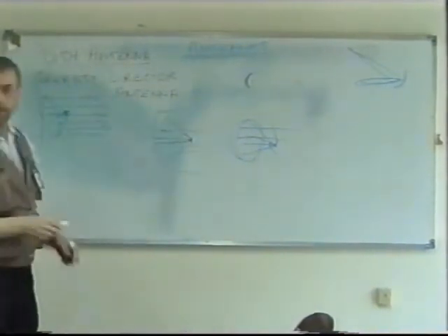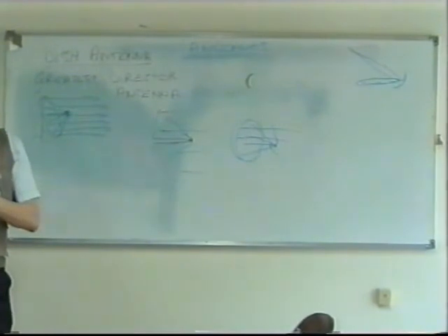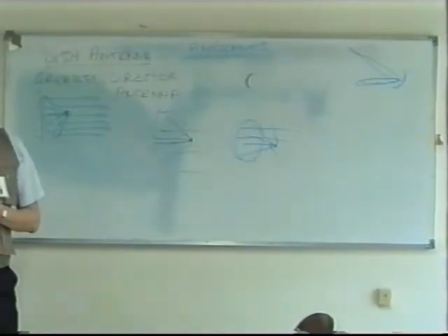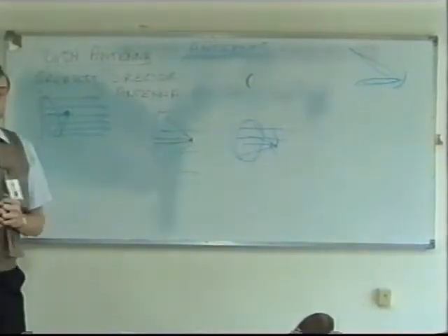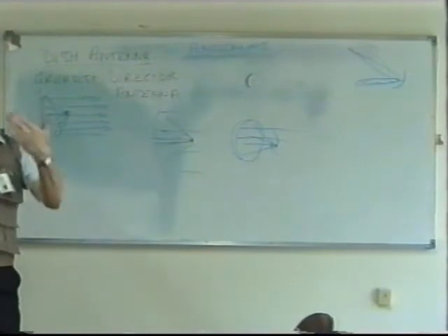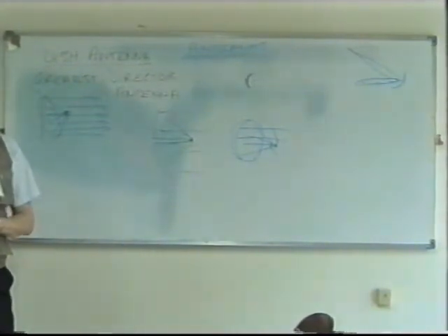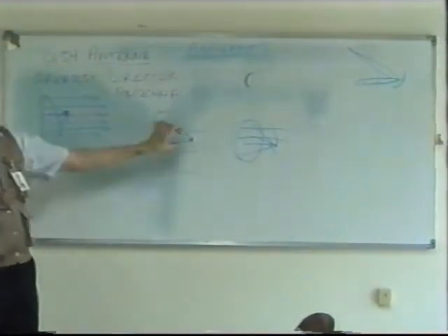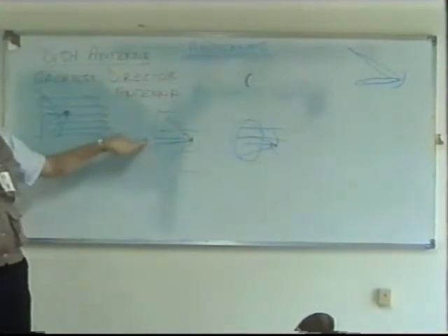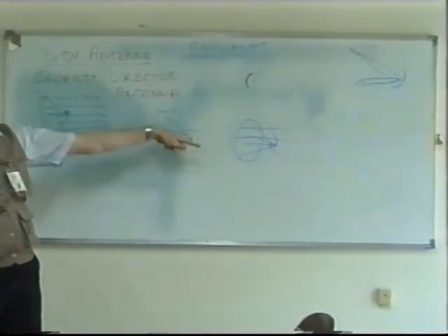And can we say this antenna is RX? It can be receiver or transmitter. In my explanation I assume a transmitter, but whatever I say about a transmitter, just the reverse will happen for the receiver in its simplest form. But you see what's going to happen? We haven't now got a perfect dish. We've got an imperfect dish because we've got a hole at the back here with this thing pushing through.